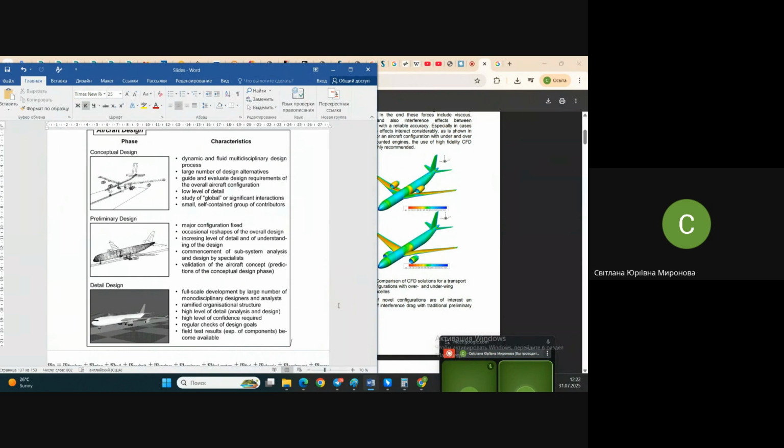So the power plant should be quite enough for cruise flight. For takeoff, it should have some reserve, an additional amount of capacity, and partially we solve it with the power plant, partially with other decisions, for instance, using high lift devices. On the other hand, during the cruise flight, the power plant is used to provide thrust, but it also has some auxiliary purposes.